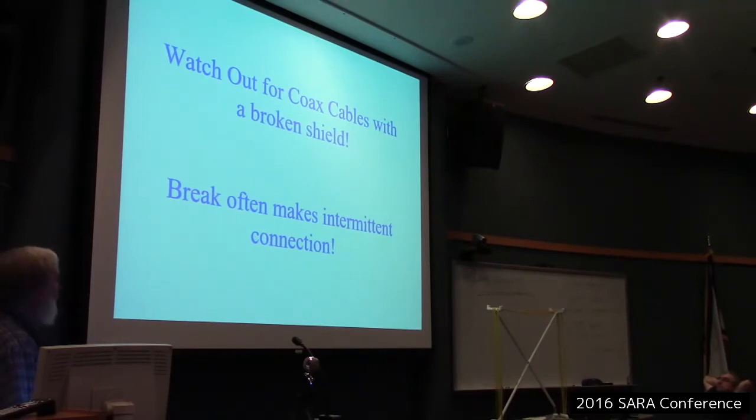If I have to run something a long distance, I would convert 232 to 422, so I get differential signals, and they go through the 100 feet of wire out to my antenna where I have to control something. I would not run an RS-232 more than about 10 feet personally. I mean, it's great for hooking a local device to the computer, except, well, computers don't have an RS-232 port. You have to put a dongle device on there.